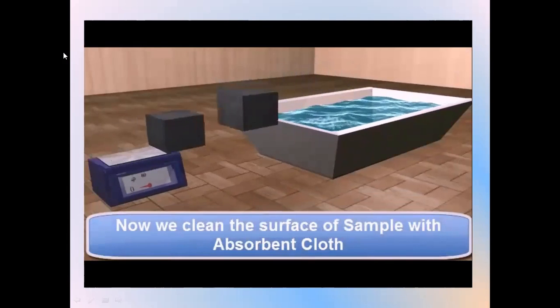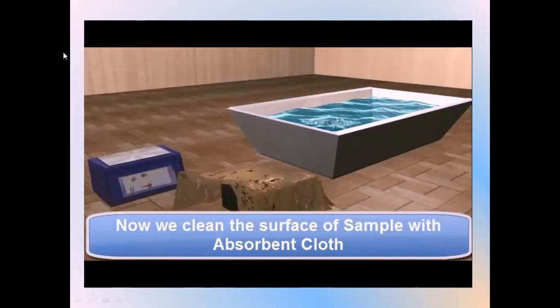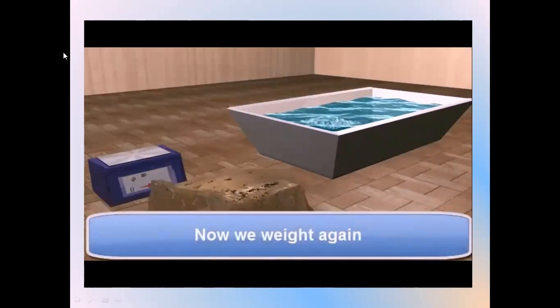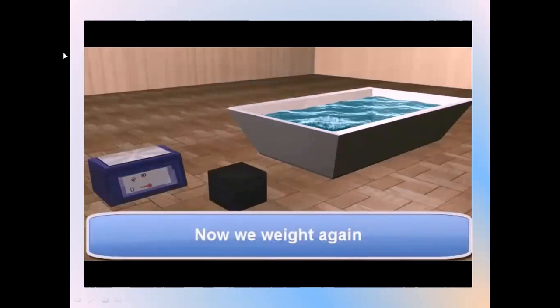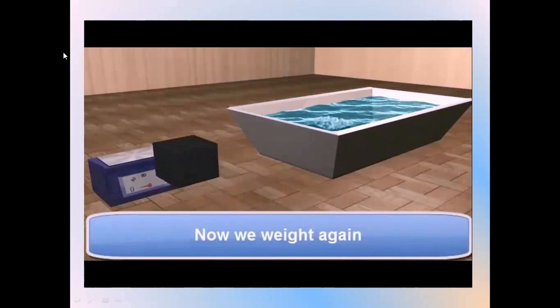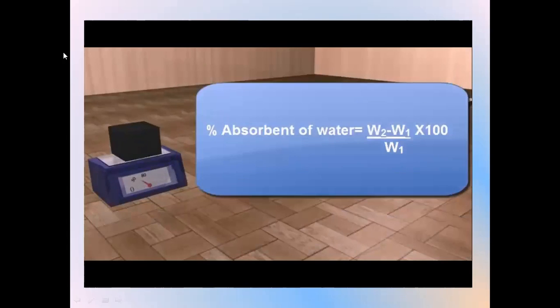Then the stone sample is taken out and cleaned with a cloth so that the excess water on the surface is removed. Now it is weighed again, called W2, and the water absorption is found out.